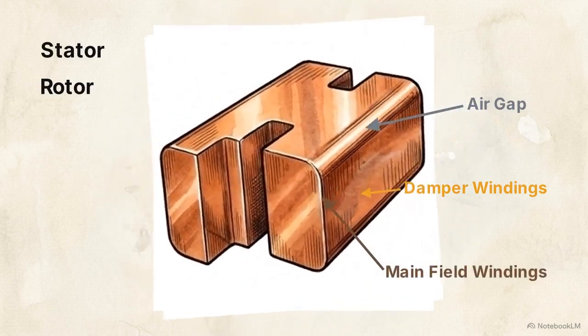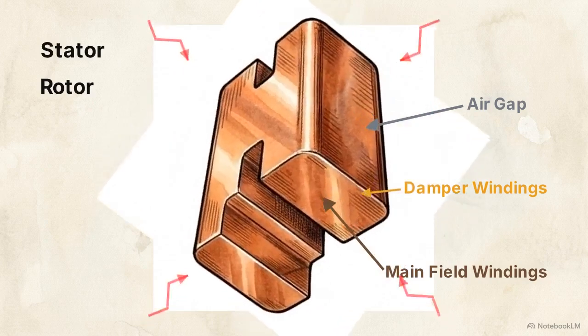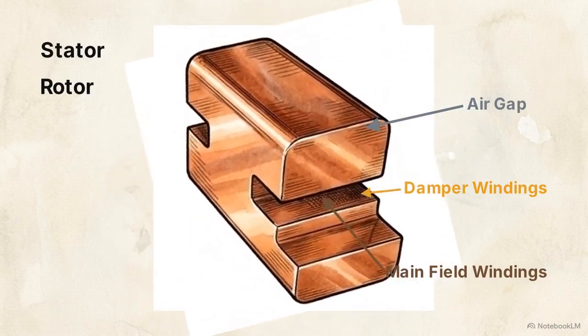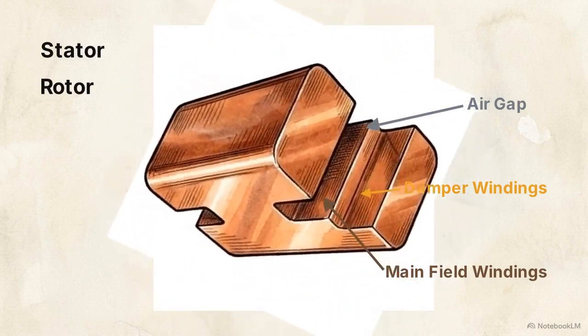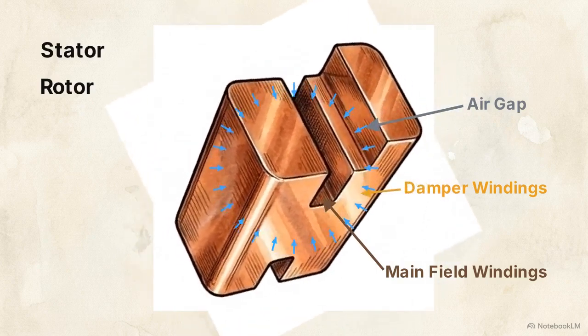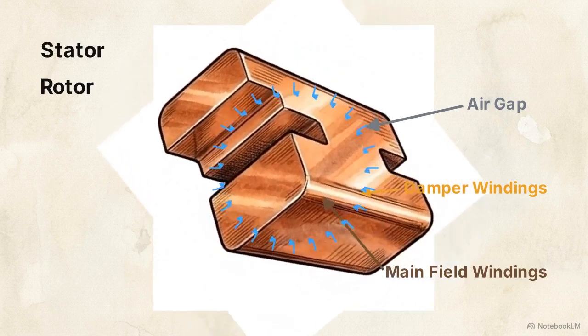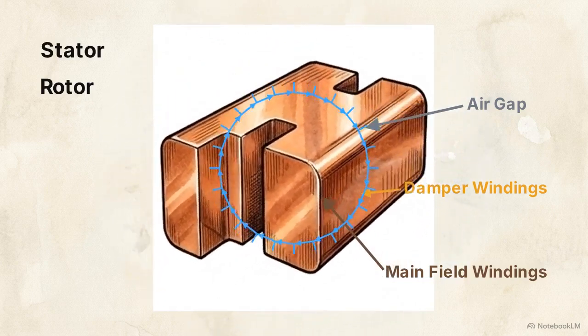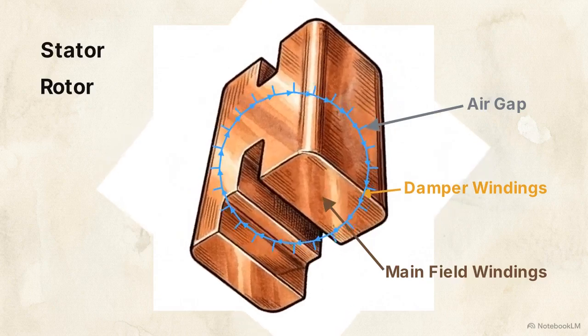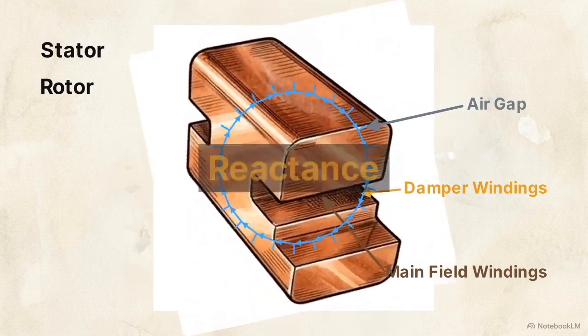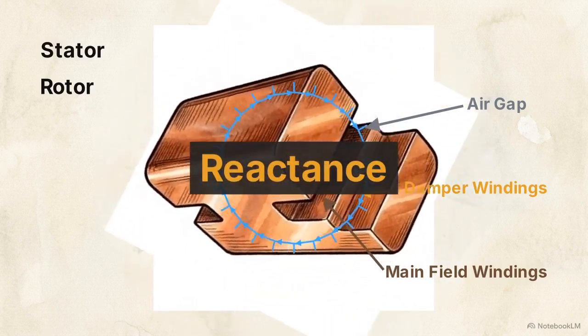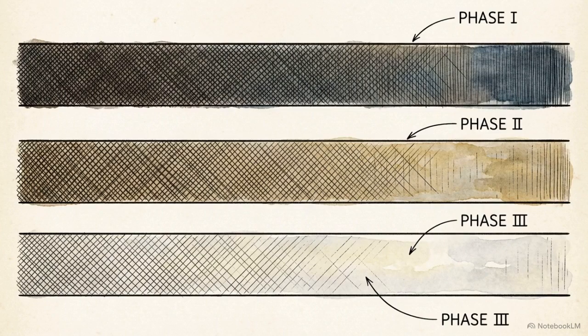At the exact millisecond a short circuit occurs, the stator demands a massive, instantaneous increase in current. This generates a sudden surge of magnetic flux that attempts to cross the air gap and penetrate the spinning rotor. The rotor's internal magnetic circuits provide physical opposition to this armature flux, forcing it to bend into high-reluctance leakage paths. This opposition is defined as reactance. This magnetic opposition weakens through three strict temporal phases: subtransient, transient, and steady state.